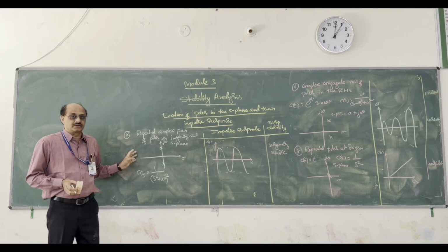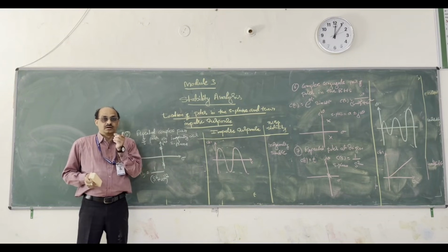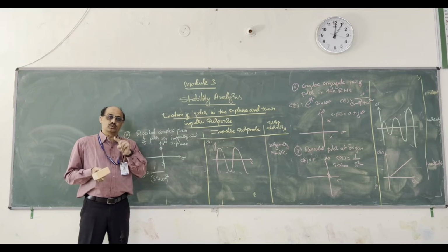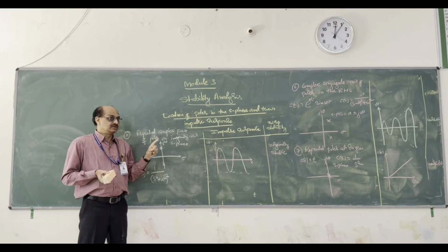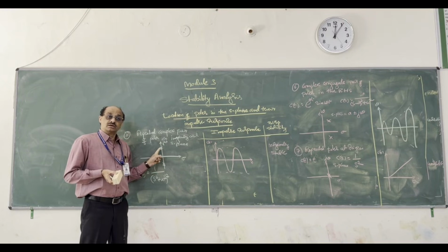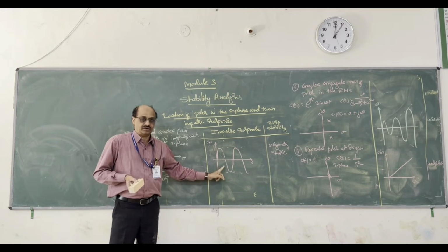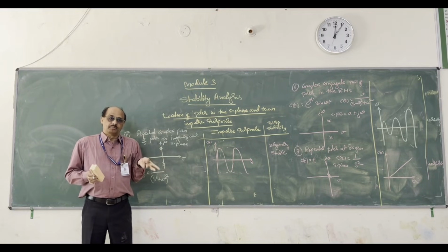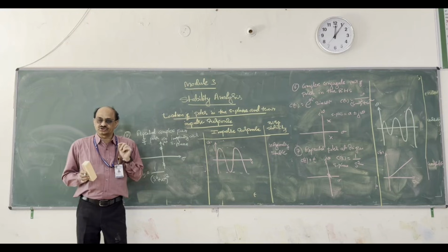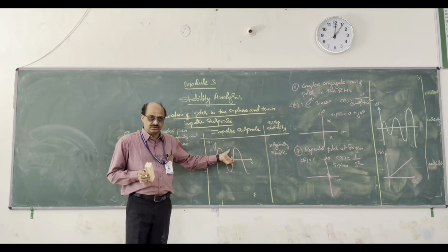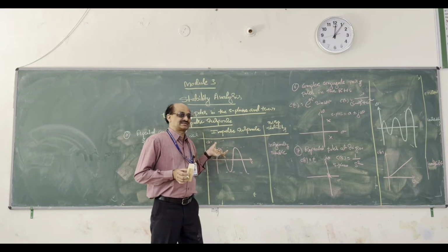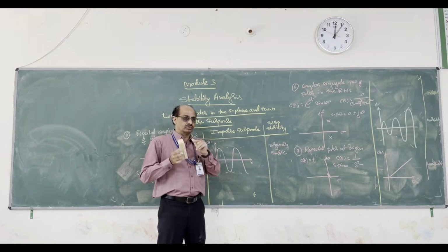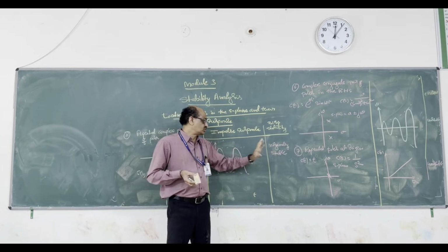So again you need to compare that with a single complex conjugate group, or non-repeated poles. Remember, this is very clear. If I have only one single pair of poles on the imaginary axis, it gives you sustained oscillation or undamped oscillation. Sustained means constant magnitude: oscillation with constant magnitude. It's marginally stable.